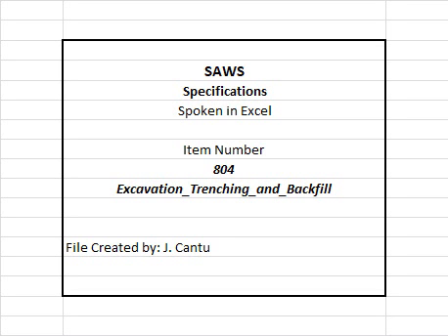N. Trench supports are exclusive of the minimum trench width. O. The maximum allowable base width of trench shall be not greater than 24 inches than the exterior diameter of the pipe, not more than 12 inches on each side. P. Trench supports are exclusive of the maximum trench width.